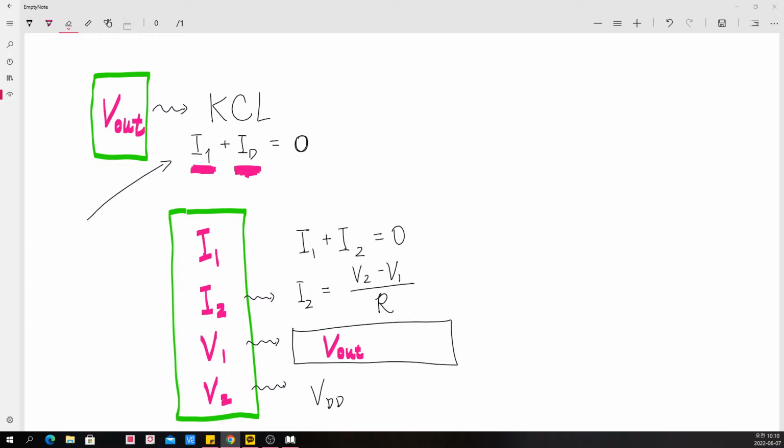No, Mr. Bach. The method you have specified in the chatting log is just one for verification. You have to introduce the coupled system. In this coupled system, your electrostatic potential, electron density, and hole density, together with the terminal currents, terminal voltages, and node voltage, should all be included in your general large system.